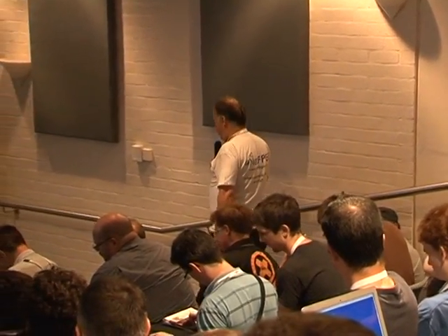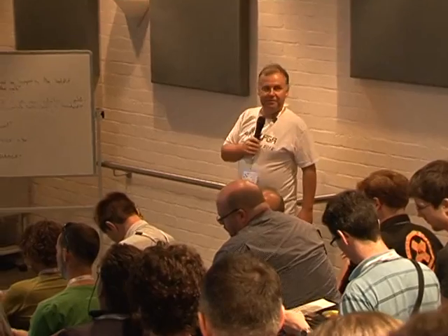So I haven't thought about channel bonding at all. The intention is to have one USB port per Tegra CPU. Haven't actually considered whether you'd need more bandwidth. But as far as I know, the Tegra CPU only has a single USB controller, so bonding USB wouldn't get you anything. If you could bond it with some other interface that's available, you might get some extra. But the Tegra 2 itself only has a single USB channel.